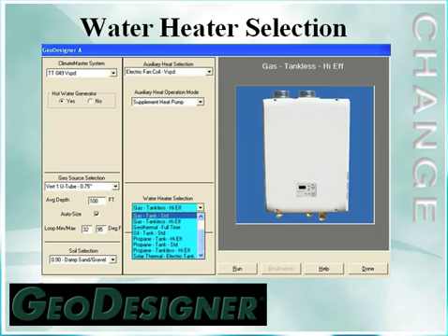And then our last input is what is our water heater selection. With the hot water generator desuperheater feature, we're typically going to do about 50% of their annual water heating. However, during the spring and the fall, during the mild conditions, when the geothermal unit doesn't run very often to heat or cool the building, we use a backup water heating method to make sure our customer still has hot water at all times. There are numerous selections on here for the water heating options. We could actually do a full-time water-to-water geothermal unit that would do on-demand domestic hot water heating for them.